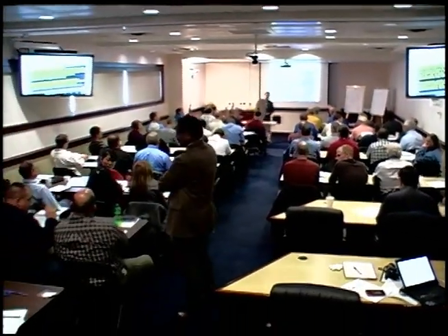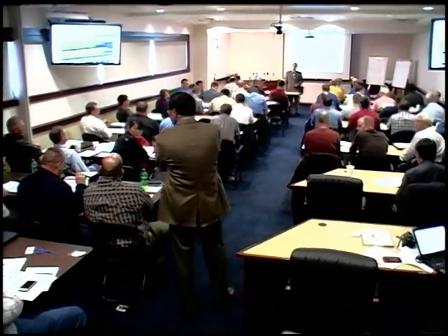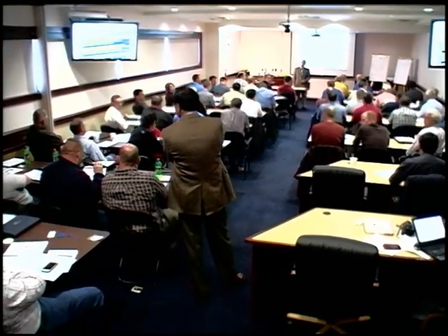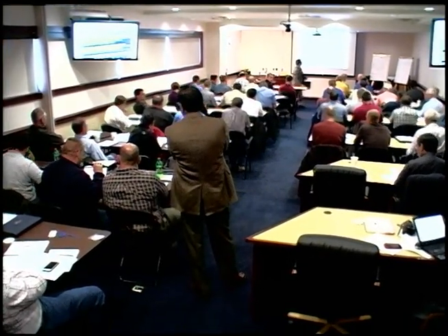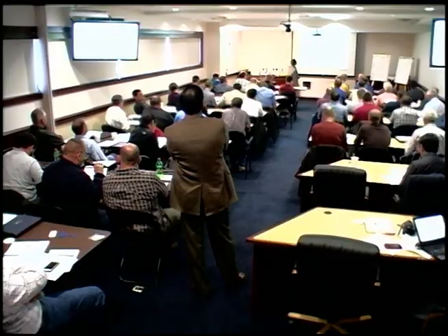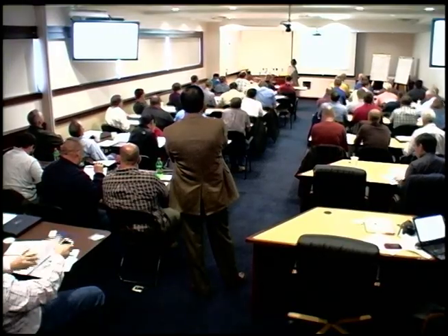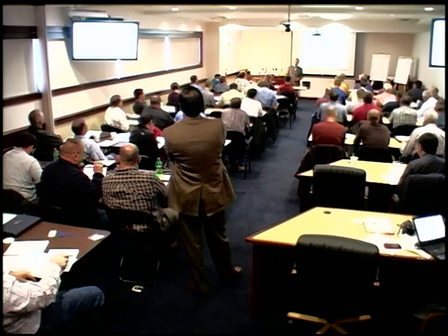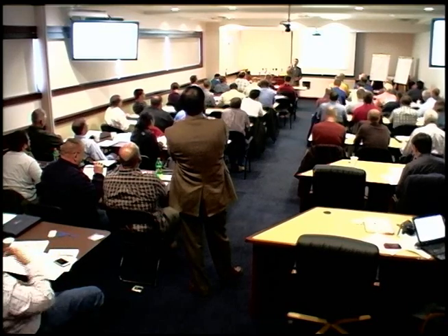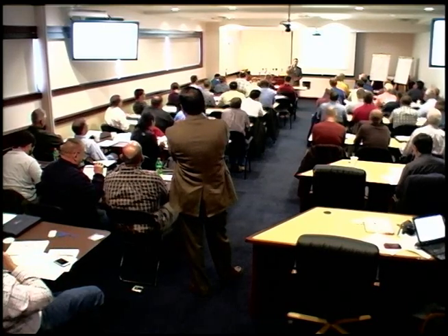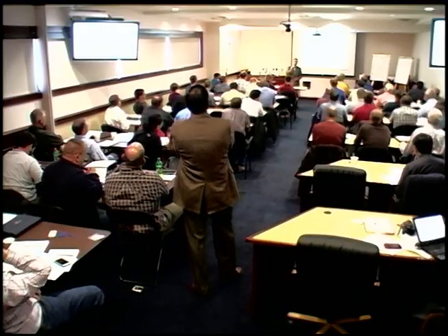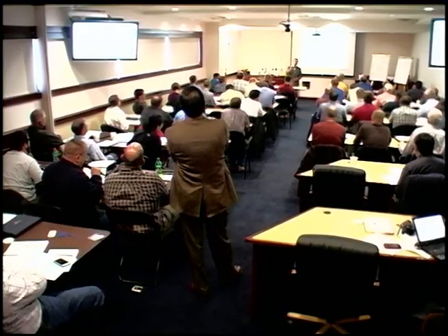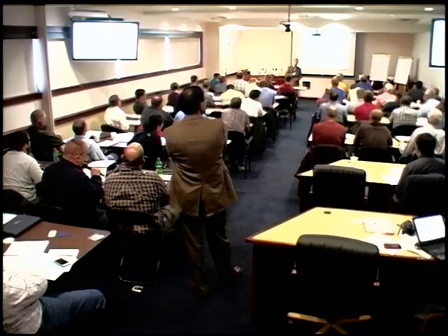And this might address Mike's thing, because on step 6 you're dealing with 108 kips. That's what you need to determine the contract length. It's not the number that you need to verify the pile performance at the site.